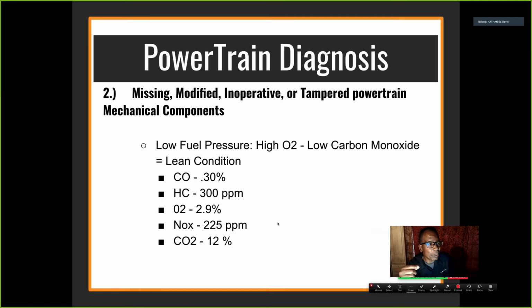And the other one I was just thinking about, yes, this is the other way. The O2 sensor can pick up bad O2 and give a rich command. It could do that by an exhaust leak right in front of the O2 sensor. It thinks it's running lean when it's not.